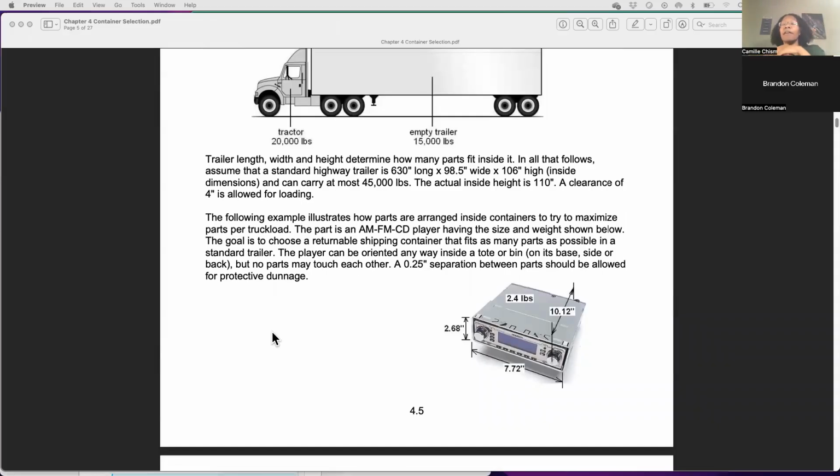So I've seen things where you have parts that have an A surface and a clip. And if you just take the general dimensions of that part and you use one of these programs, it might put them upright and nest them together. So the clips are going here, or it might nest them this way, so the clip is touching the A surface. The program doesn't necessarily know which parts are A surfaces and which parts shouldn't touch.